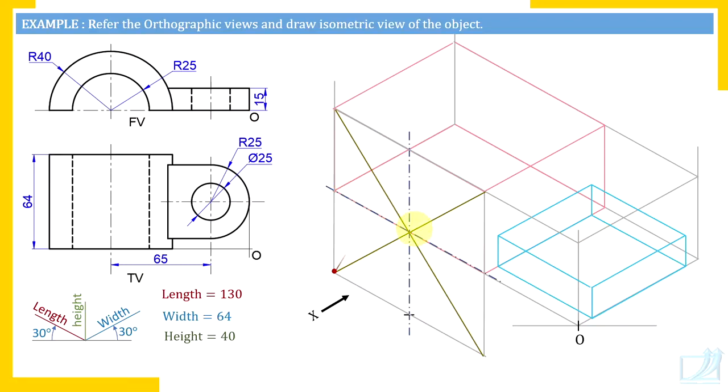Watch here what I am telling you. So here I have joined this end of the shorter diagonal with midpoint of opposite edge. You can join on this side also, but remember, we are not drawing the entire circle. We are drawing semicircle. So for entire circle, 2 longer arcs, 2 shorter arcs. But for semicircle, 1 longer arc, 1 shorter arc. So in this portion, this is that surface which is semicircle. So here you will get a longer arc.